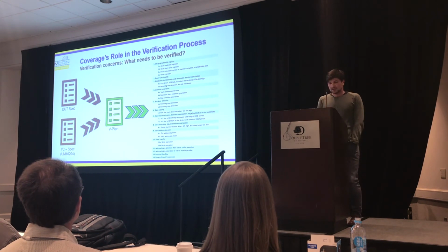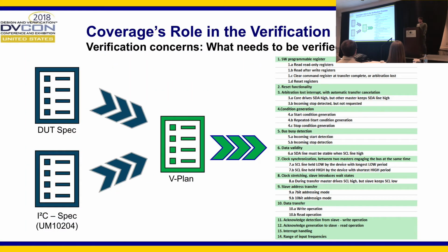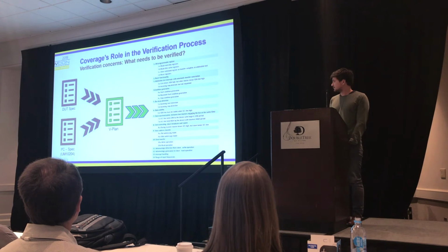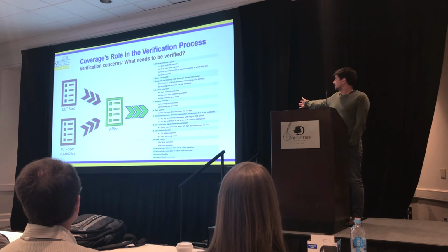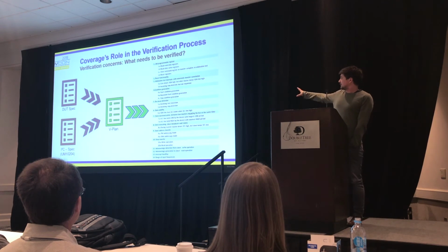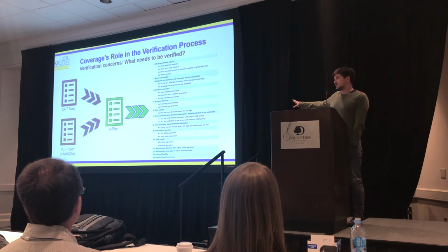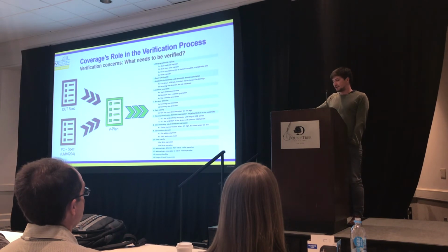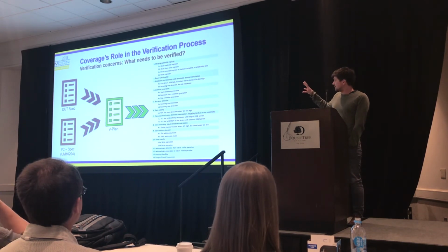So where do we start? First of all, you have to decide what your verification concerns are for the design you pick, and what needs to be verified. For this, you have to rely on specifications. In our case, we had two papers: the design specification and the I2C spec, from which we derived a verification plan that you can see on the right side of the slide. It covers all the functionality presented in the design, not only the I2C protocol, so this is an end-to-end verification. The goal was to verify each bullet in this verification plan.